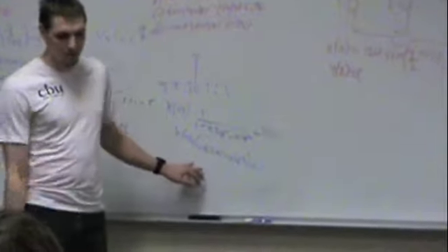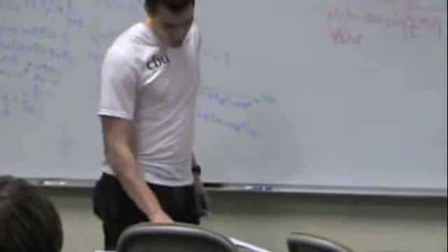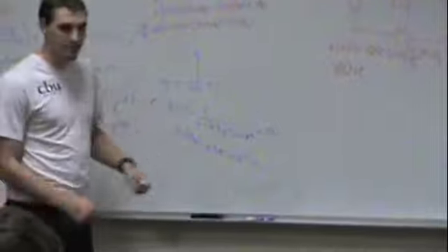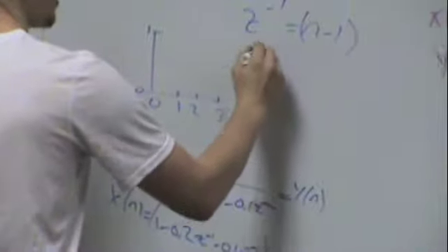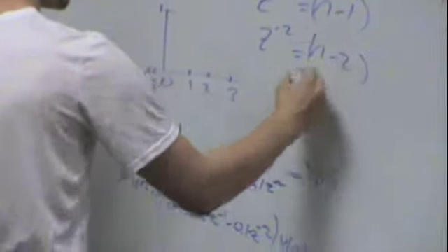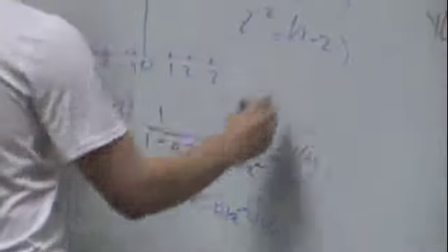You do the inverse Z transform of this, which is basically converting Z minus 1 to n minus 1, and Z minus 2 to n minus 2. Is that looking familiar? We take this and plug it into all the Z's, and then you just plug in an impulse function. So we know that x of 0 is 1, and everything else is 0.